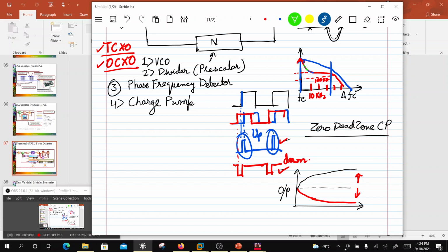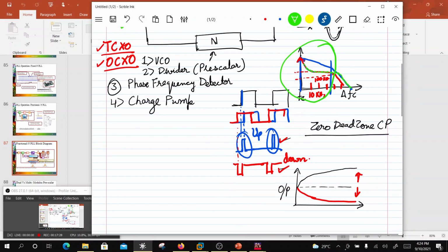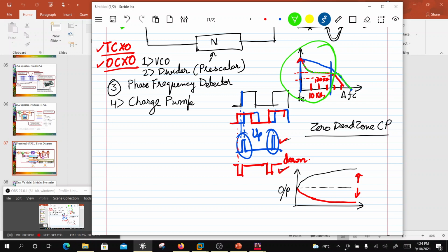So this is going to follow the crystal, and then after that it catches with the VCO, right? So in this region, which is the loop bandwidth, the phase noise of this source is the same as the phase noise of the reference signal. So that's the idea here.